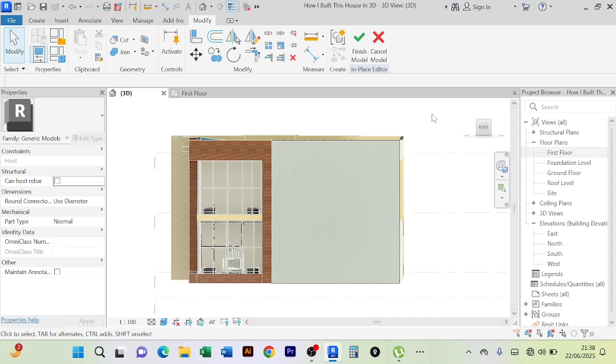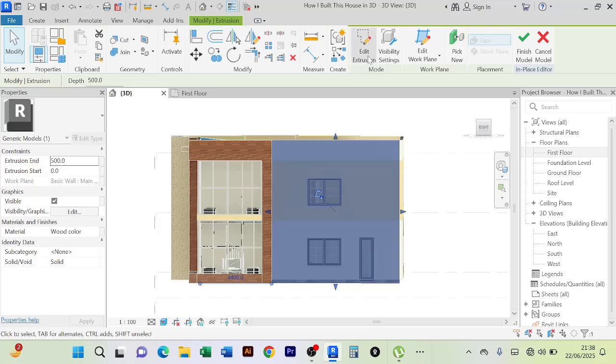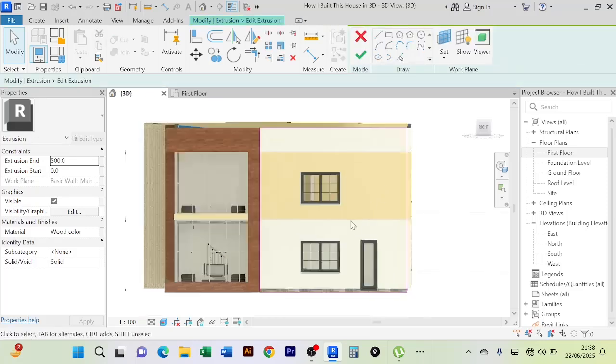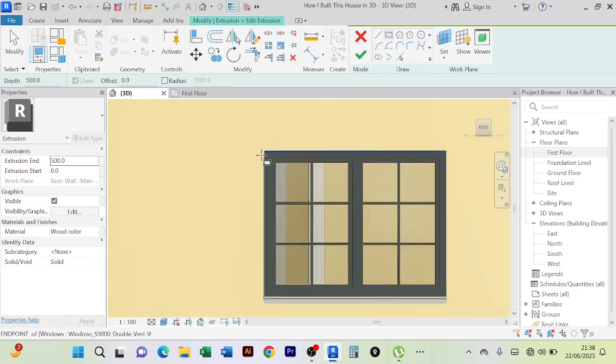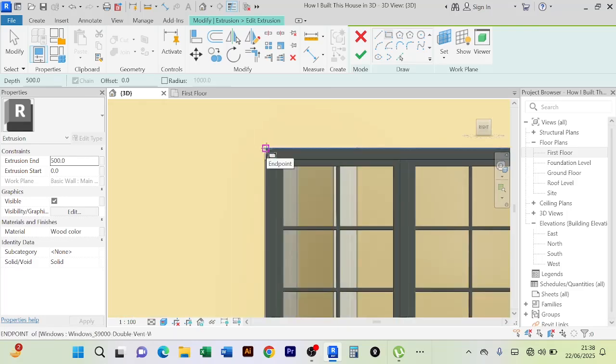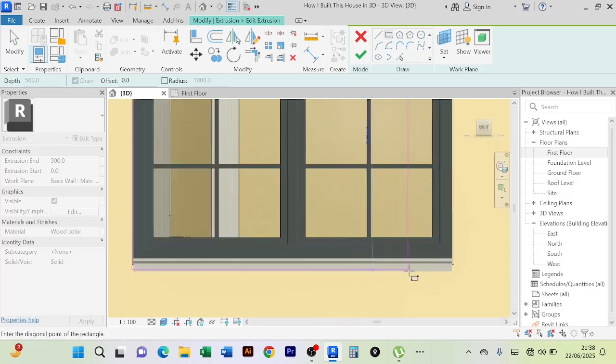That one is for the wall, so it's not active for extrusion, but we shall use either void, or we shall just edit in place. But I always prefer to edit in place. You just say edit extrusion, it is way easier for me. But depending on what you prefer, you may always use the option that is easier for you.